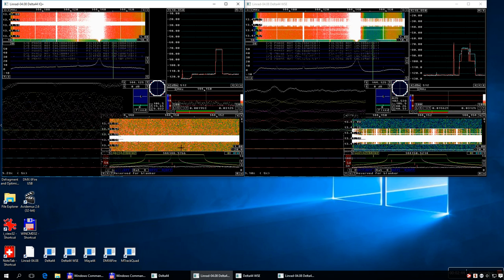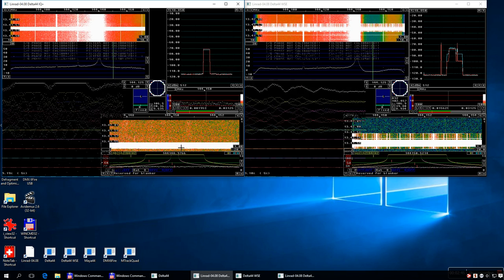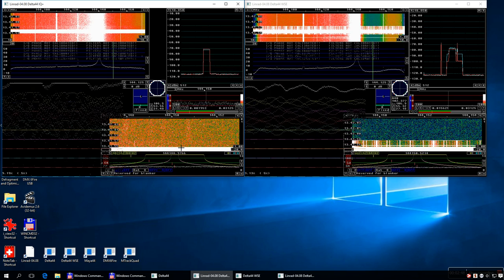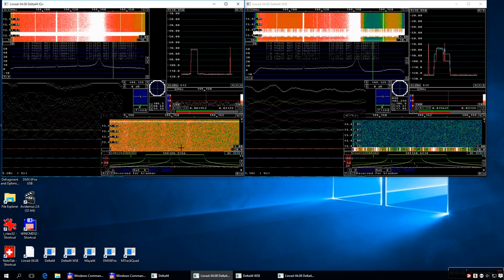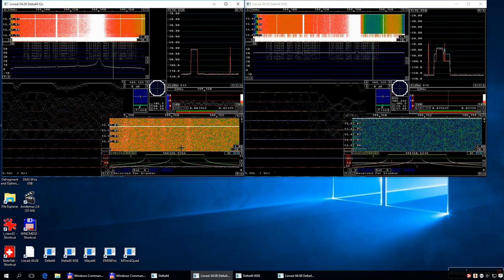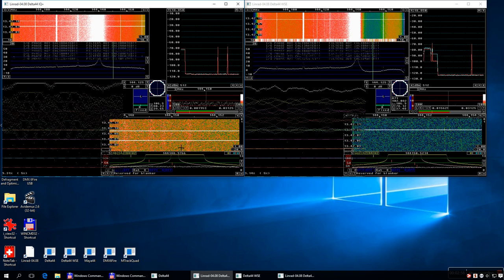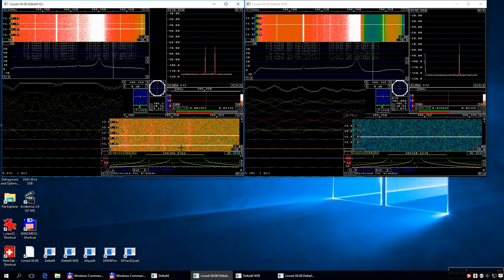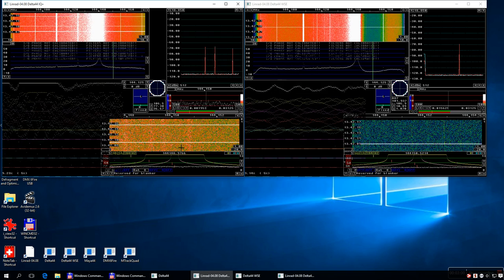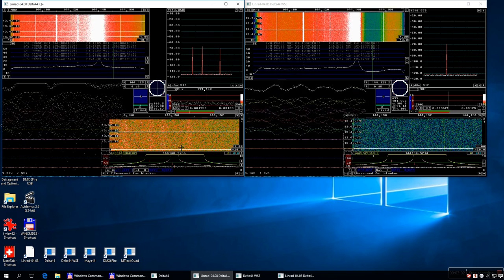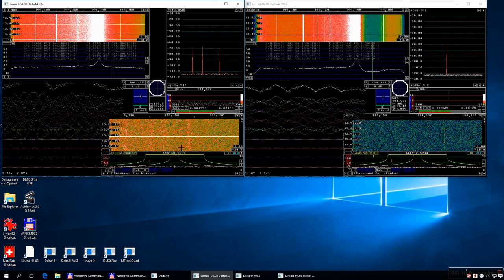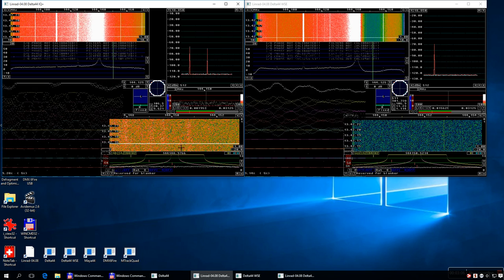The frequency response is different between the two, so saturation differs by 1 dB, 10 kilohertz lower. Now you can see in the IQ Plus the noise floor is very high on all frequencies, but on the WSE it's different.